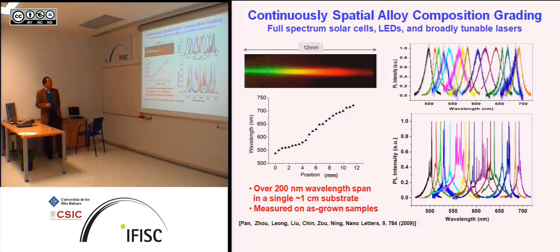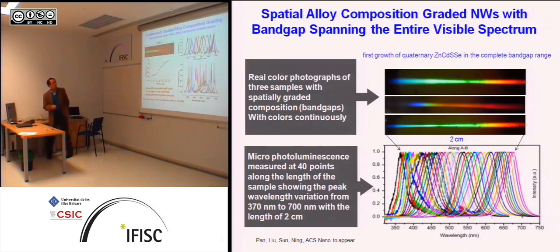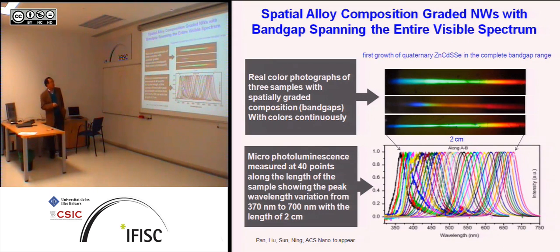The interesting thing was that because this is optical pumping, if you drive harder, what you see is that every point actually becomes lasing, as indicated here. So what you have here is almost like a spatially tunable laser over a 200 nanometer range. That's something obviously very exciting to have. Of course, this is optical pump, so it will be a big challenge to make this electrical injection, but that would be great.